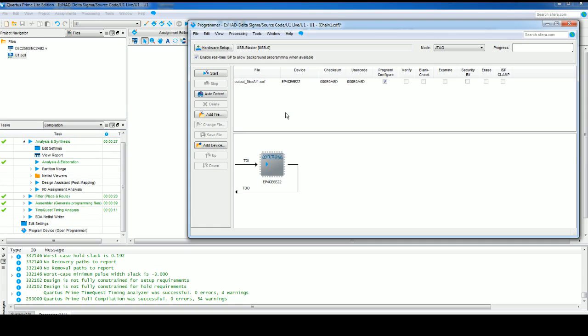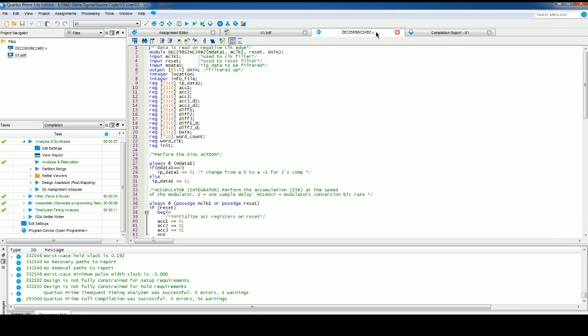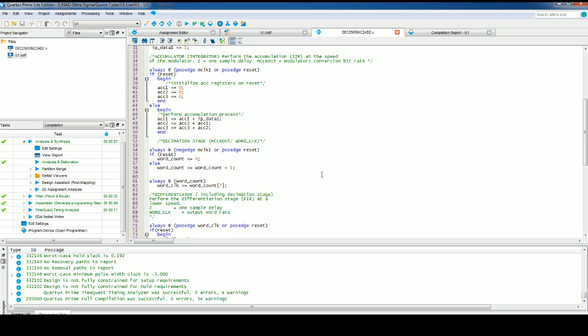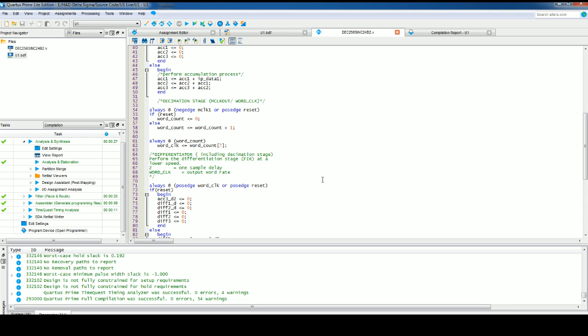Output files and start. Okay. It's now running on the bench doing that piece of Verilog code that we looked at. This code right here. And that's one way to get your digital filter. And again, we talked about what FPGAs are good for. Well, this is one of the things. You could have whole bunches of these running in parallel, all kinds of things. Remember, code typically can't work in parallel. Code works a single instruction at a time. By code, I mean in a microprocessor.